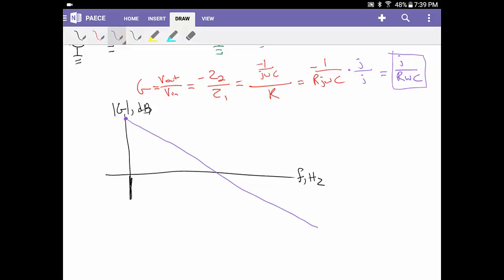So, is this something that we really want in our circuits for filtering? I personally say no, and the major reason why is because if we cared about frequencies from, let's say, 1 hertz to a kilohertz, and we have 1 hertz here and 1 kilohertz here on our frequency plot, what's going to end up happening is my 1 hertz signal is going to have some ungodly amount of gain when it goes through this system, but our 1 kilohertz signal isn't going to be as amplified. So you don't have a linear passband, meaning that you don't have a really nice flat range of gains for the frequencies that you care about. And this is kind of a pain to design around.